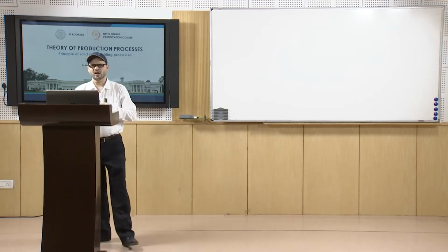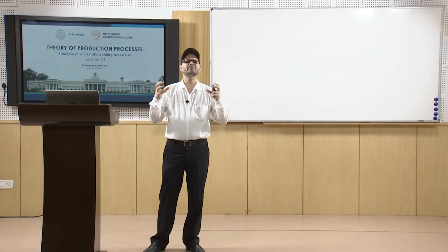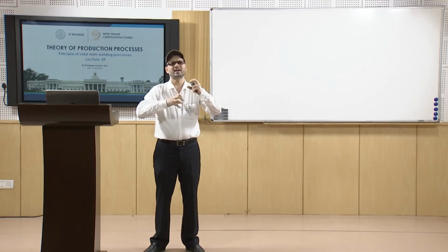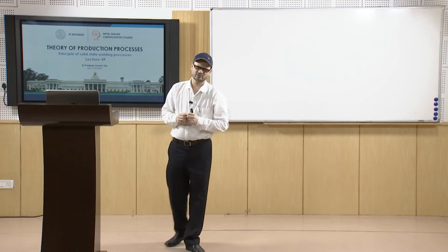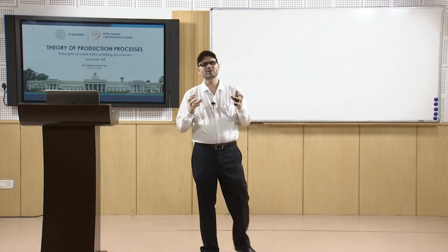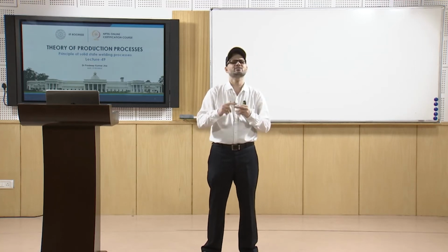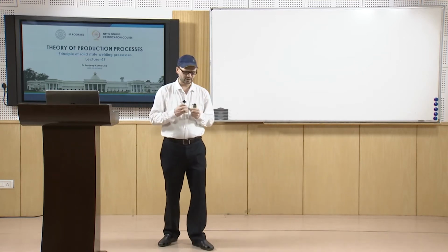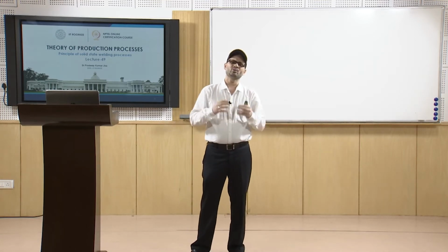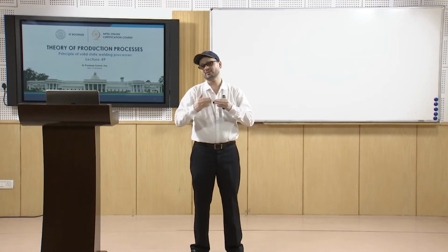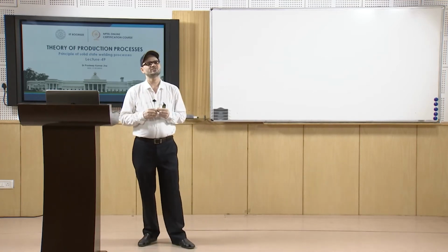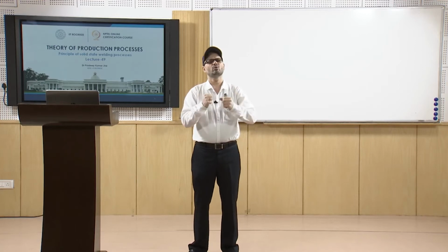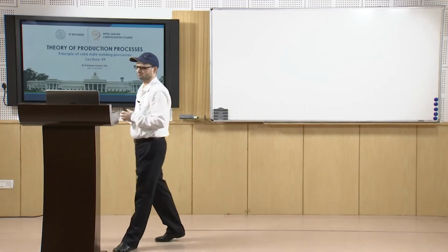The friction will be generated because of the relative motion between the two. One may be stationary, another may rotate, and then that may be brought in touch with the next one. Once you have relative motion between them, friction will be generated at that surface, and because of this friction, heat will be generated. Slowly, when the temperature reaches so high, plastic deformation may start, and at that time bonding takes place because of the force which is applied on the two materials.